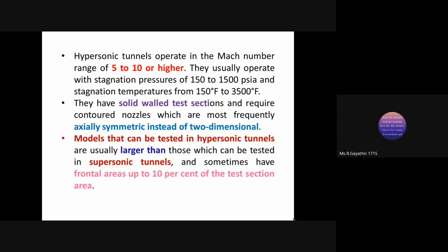Okay, next about the model sizing. Okay, we can choose larger model, comparatively larger than supersonic tunnel model. Sometimes the model frontal area sizing is up to 10% of the test section area.